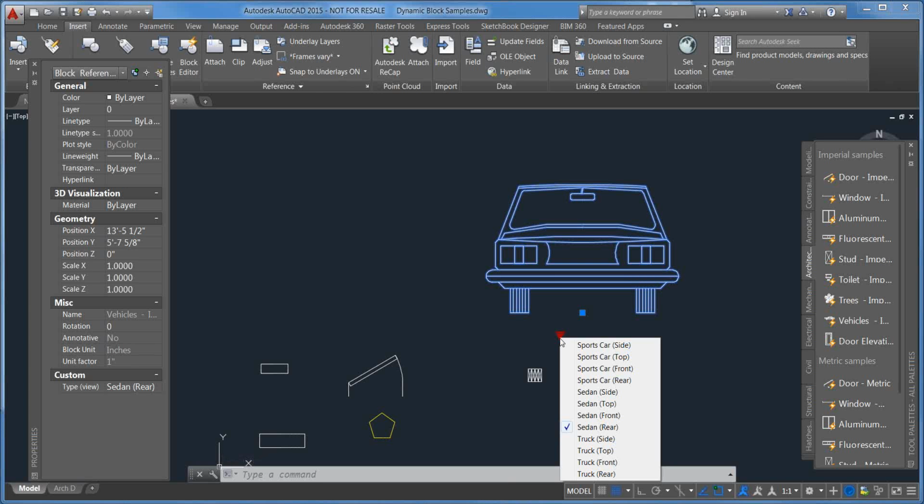It has to store all the line work. Now, if that is very complex geometry, then you're absolutely right. That could tend to start bloating your file size if you have lots of dynamic blocks with lots of different states built into them. So thank you for mentioning that. That probably is a consideration when you're starting to make these dynamic blocks. How heavy is that block going to get? It's probably worth adding up the size of the individual blocks, and that is the end result of the dynamic block.